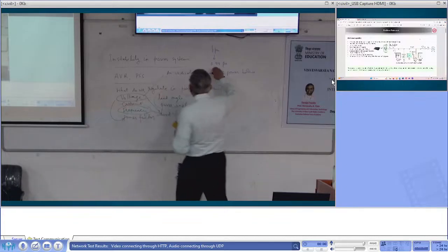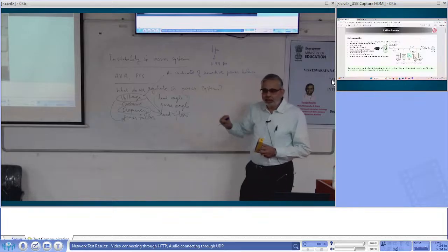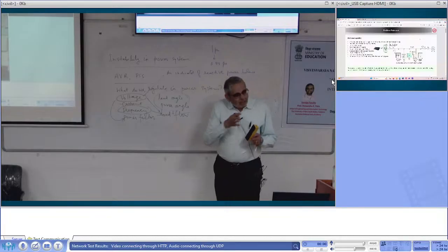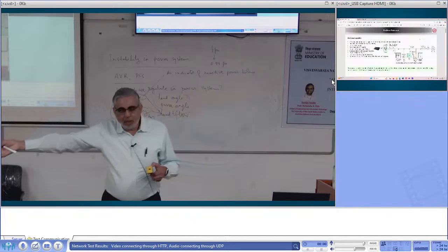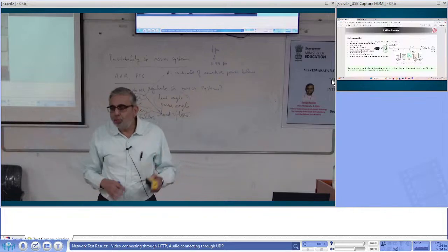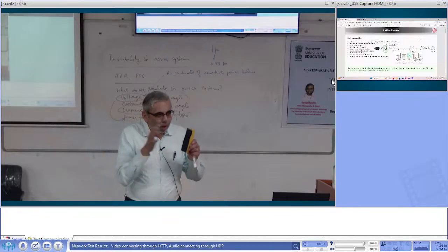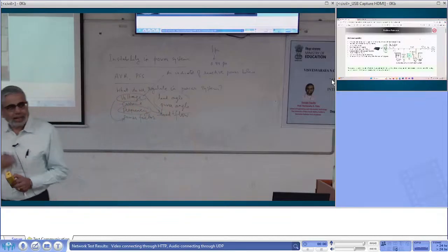So if I reduce the voltage here, my transmission line reactive power consumption will decrease, and whatever I am generating will be enough for the new load which has come and the transmission line. So it will redistribute the reactive power consumption of the network to come to a new voltage level. Okay? So that's how 0.99 helps.